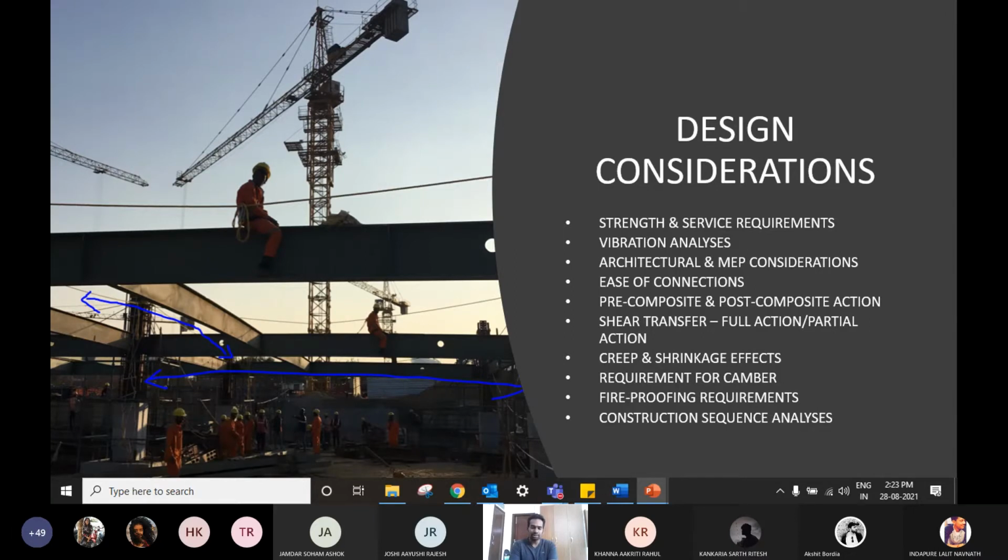Now when you do a vibration analysis check, there are some formulas and some software which does the vibration analysis based on the walking frequency of the people working there. If it's an office building, what's the frequency which can hit because of walking, because of the live loads, and that should not match your inherent frequency. You remember the resonance concept that we saw: your excitation frequency, basically your building occupancy frequency, people walking, running, and machinery running, should not match your structure's frequency, right?